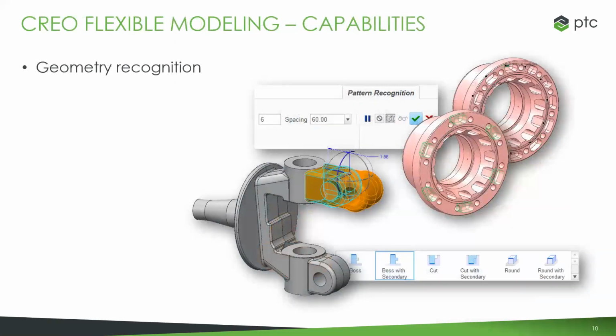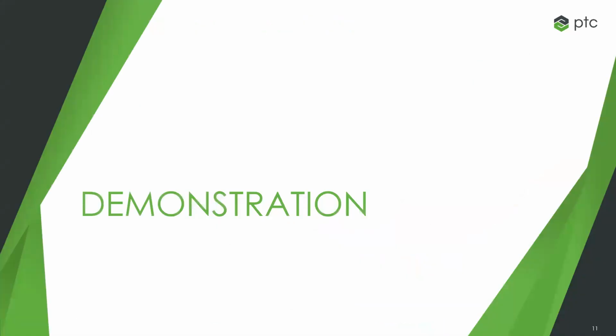So in the process, what you're doing is taking pieces of the model and recognizing the geometry. And once you have those features recognized, you're able to change them, move them around, modify parameters, and all of that's done regardless of how the model was built initially, right? It could be any type of model. We don't require much information to get started in that process. And the next step is really just making all of your changes in your normal 3D CAD modeling and editing, to move features around, rotate things. And once you've created these features, there are options, of course, for propagating those throughout the model as well.